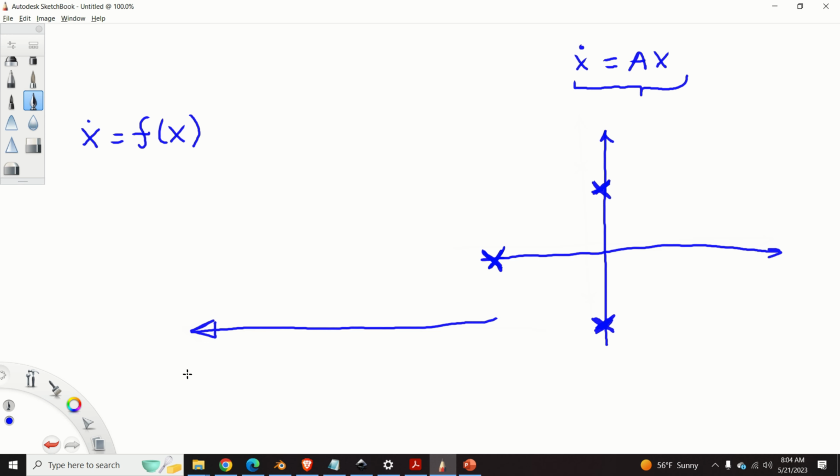This is also an indefinite case. So to summarize the indefinite case: it happens if one or more eigenvalues of the matrix A have zero real parts and no eigenvalues with positive real parts. The stability of the equilibrium point of the nonlinear system cannot be analyzed. So keep in mind this.